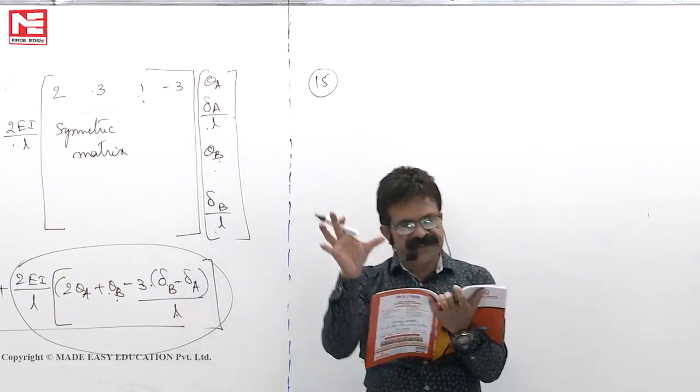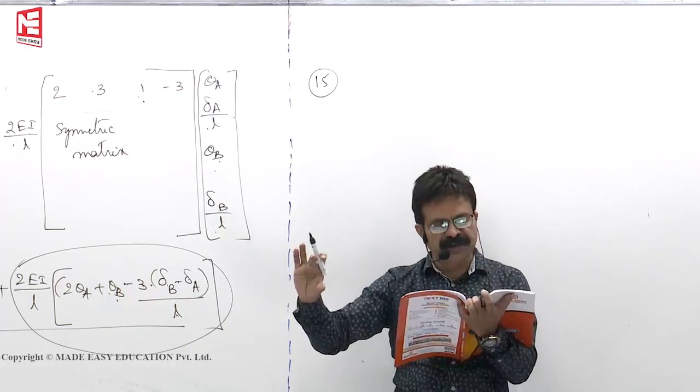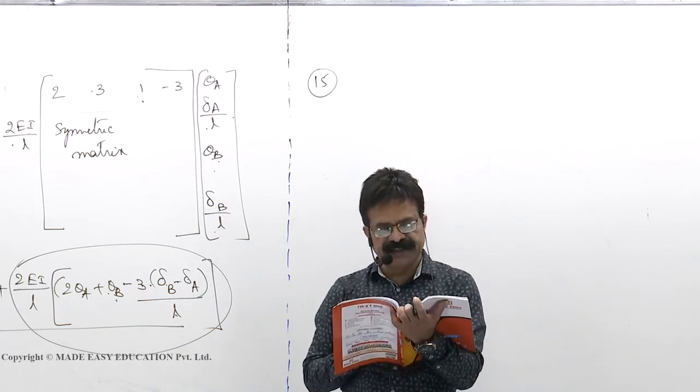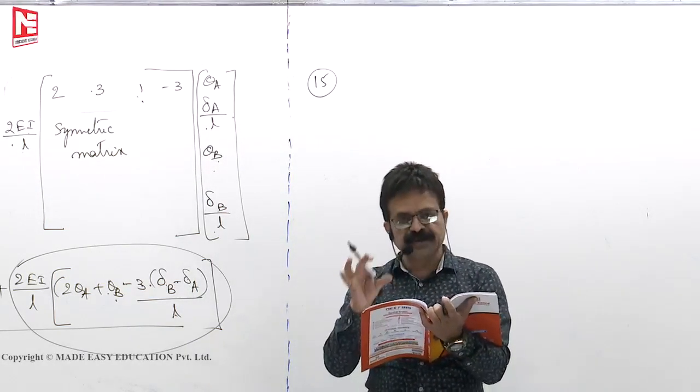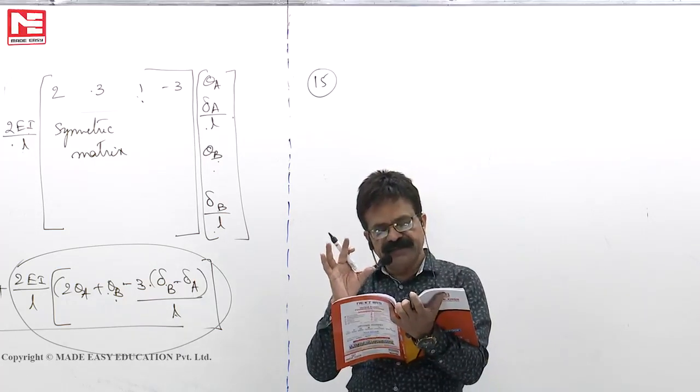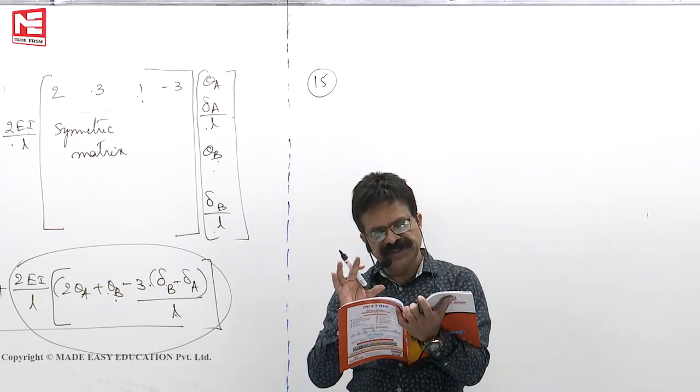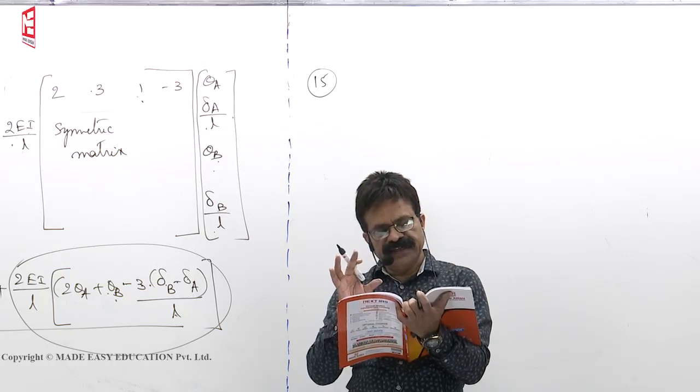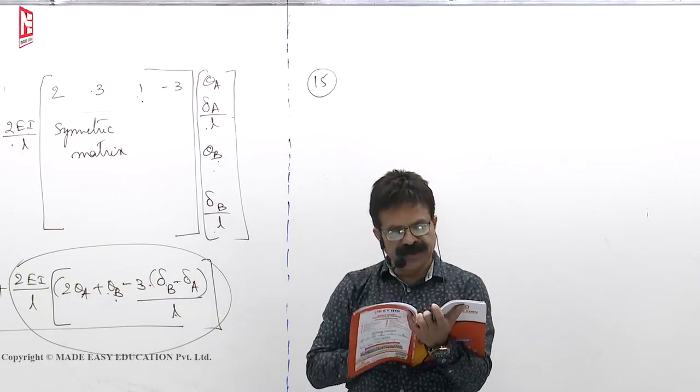In a portal frame of single bay, the columns have different thermal coefficients of expansion. Alpha is different. If the whole frame is subjected to the same temperature, there will be a component of deformation in the vertical direction. There will be a component of deformation.